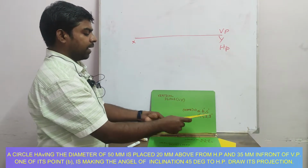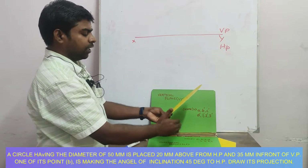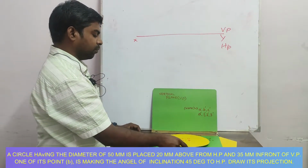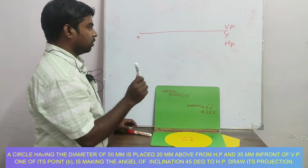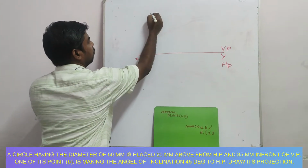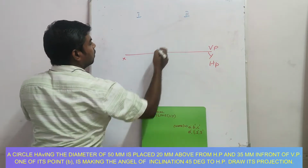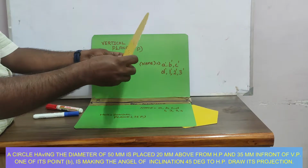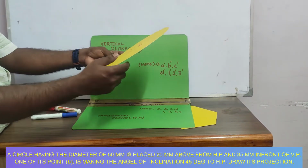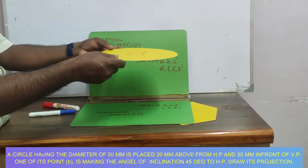Here it's going to make an angle of inclination 45 degrees with respect to HP, right? So we are making that position only, and there is no more inclination with respect to the vertical plane. So there are two stages available, stage 1 as well as stage 2. Okay, so the disc is like this. After that only it's going to make 45 degree angle of inclination with respect to HP. So first write the normal front view and top view.